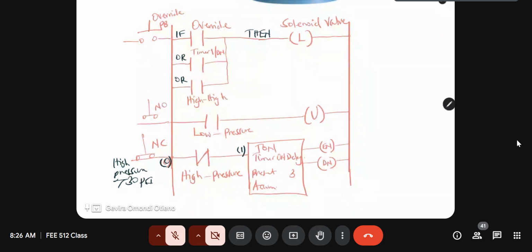So this is normally open. What we are going to do is, it is closed when the pressure is less than 10 psi. So when the pressure is less than 10 psi, you close it. When you close it, it provides a logic 1, which then unlatches, so that now the valve is closed. Yeah, so this condition is fine. And of course, the rest remains.